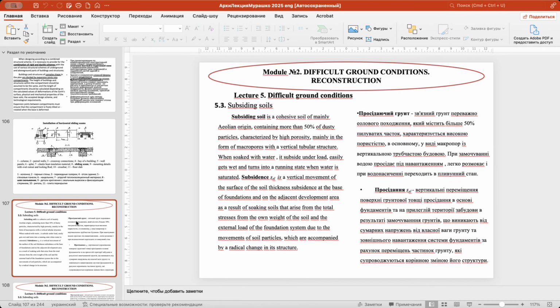Those underground mines can be caused by various works, but nevertheless they can lead to different deformations of the surface of the ground, with curvatures, with benches, etc., and that makes us need to be informed about this, to know the classification, that the worst scenario is 1 or 1K, and the best scenario when we have undermined territories is the fourth category or 4K category, when we're talking about the classification according to the benches at the construction site.